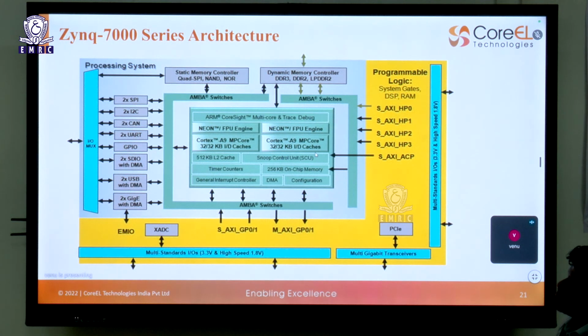All of these connections are running through a MUX. So therein falls our limitation. This MUX is only a 54-bit MUX. We will eventually run into a problem if we are using all 54 ports of my MUX. How do I extend it? If I want to add more ports for communication, how do I do it? That is where we have the flexibility of EMIO, which is extended MUX input output. MIO is going to be 54-bit, and you can extend it with another 64. So you can extend it using EMIO.